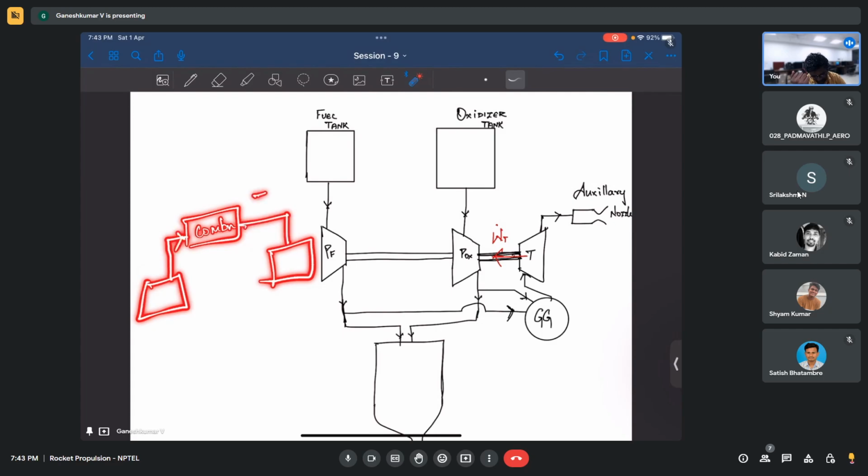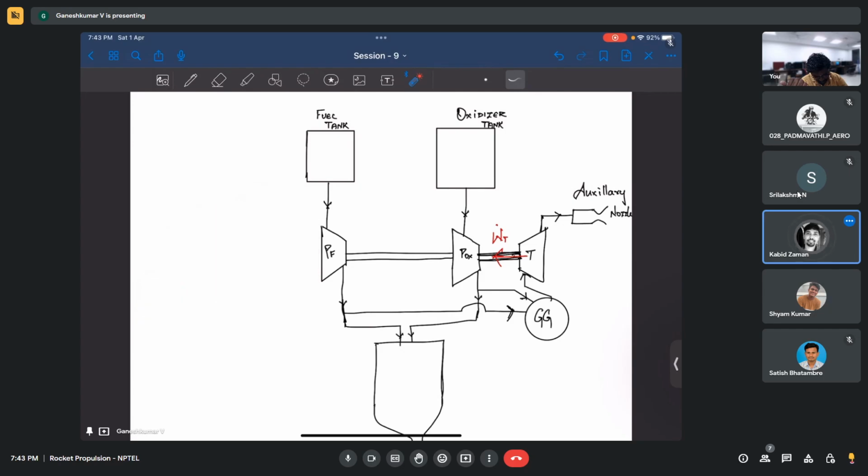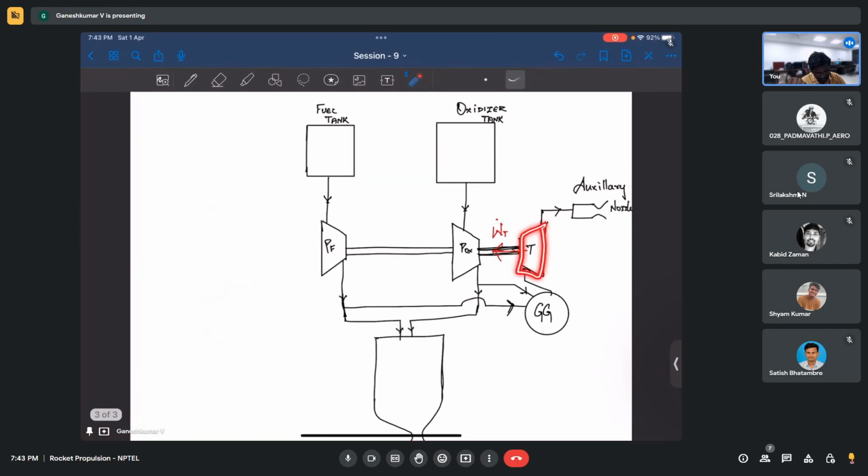And this high temperature gas outside of the combustion chamber is going to the turbine, and the turbine is going to expand, and then it's going to give it back to the pump, right? There's going to be some other thing here that extracts the heat. Heat exchanger, I guess. Exactly. So here you added the heat, here you are extracting the heat, right? That's because you made it an adiabatic expansion in the turbine.